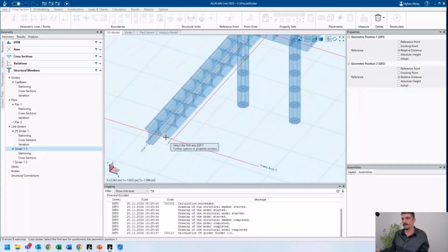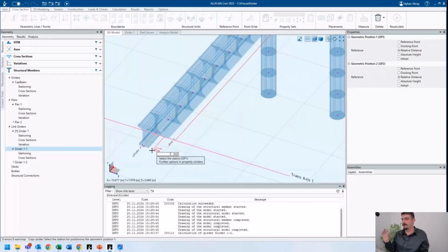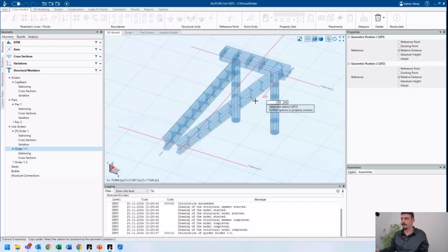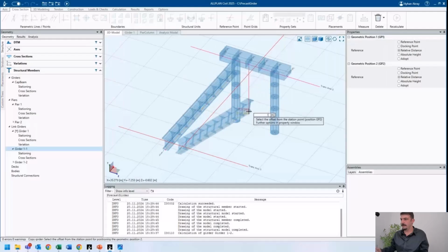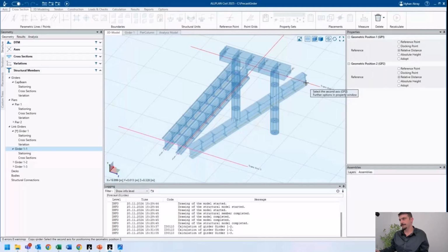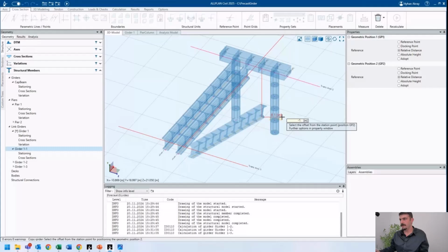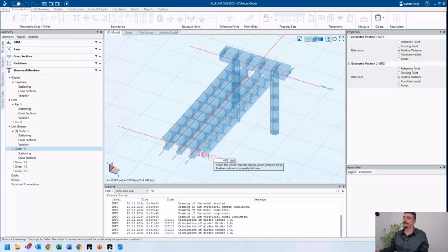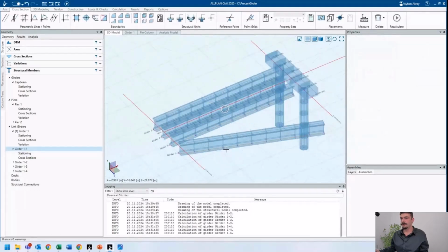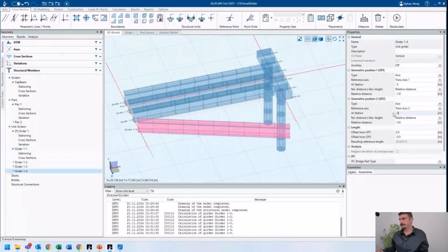So to do that, I will go to here again. I want them to be placed at a distance of 2 meters from each other, so that it was the 3 meter here. Now I will state here 1 meter. Again with the same offset. Again going to the distance axis, 1 and like this. For symmetrical purposes, I will go to distance axis and say it is -1, offset -1.9, -1, -1.9, and again -3. If you misclick something here, you can also change it from the properties menu as well. And you should recalculate it to have the action.